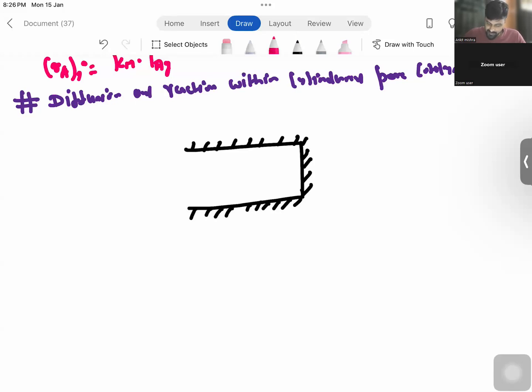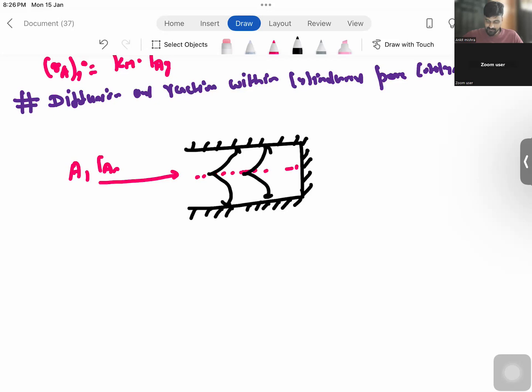So what happens? Your reactant is entering over here, let's say A, and the concentration here is CS, right? So the reactant will enter. Since the reactant will be diffusing inside the pore of the catalyst, and parallelly the reaction will be happening. So you can see the reaction is also happening parallelly with the diffusion. So let's say here at the pore mouth x equals 0, and at x equals L at the rear end of the catalyst, right? So this is how this particular thing works.